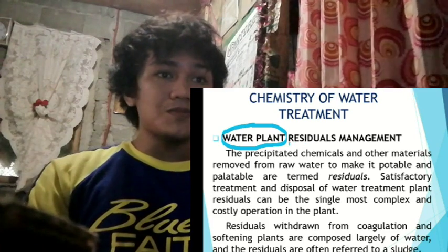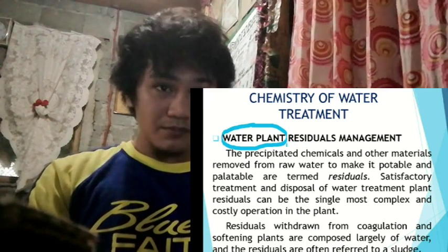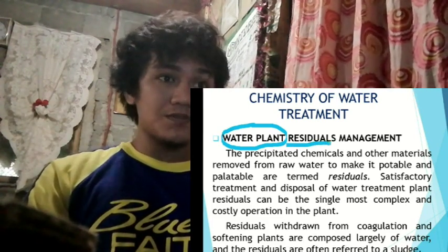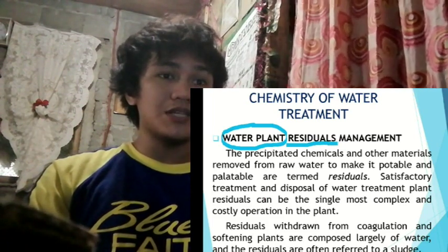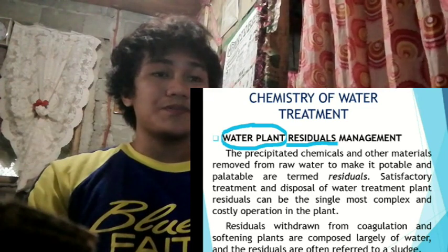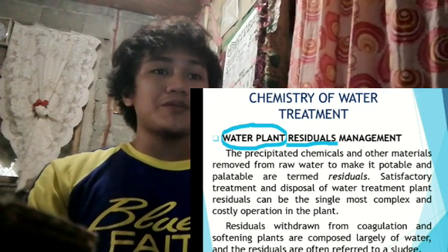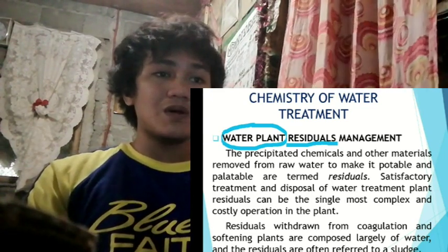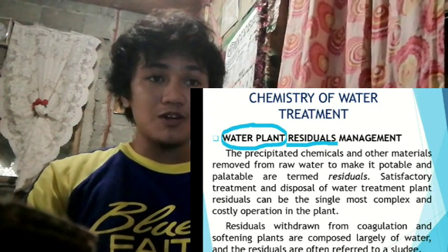The third type of plants are those that are designed to specifically remove trace inorganics such as nitrate, fluoride, radium, arsenic, and so forth. These plants use processes such as ion exchange, reverse osmosis, or adsorption. They produce liquid residuals or solid residuals such as spent adsorption material.